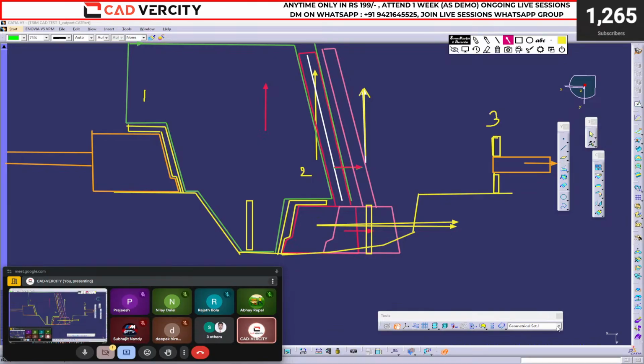Sir, why? Because in this direction you will have to clear the upper face. So the upper face will be like this, and the bottom face should be something like this. Are you getting it? Yes or no? Yes. You can't keep this face and this face at 0 degree. You will have to keep some angle, more than 0.5 degree, with respect to your lifter direction.